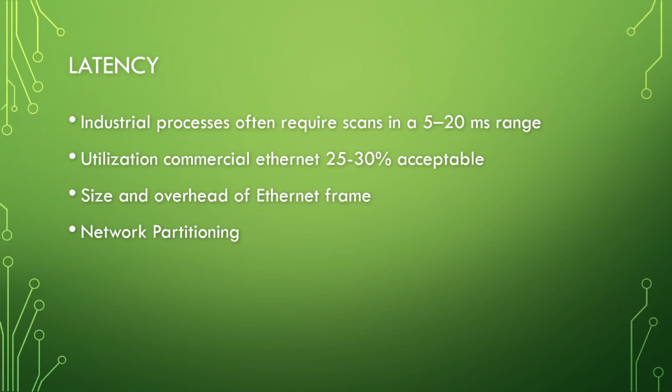That's one bit of information. You still have to send 60 bytes of information over. 60 times 8 is 480 bits. So to send 1 bit, button's been pressed, I am sending 480 over the Ethernet. So that's why latency can be a problem in the world of Ethernet.